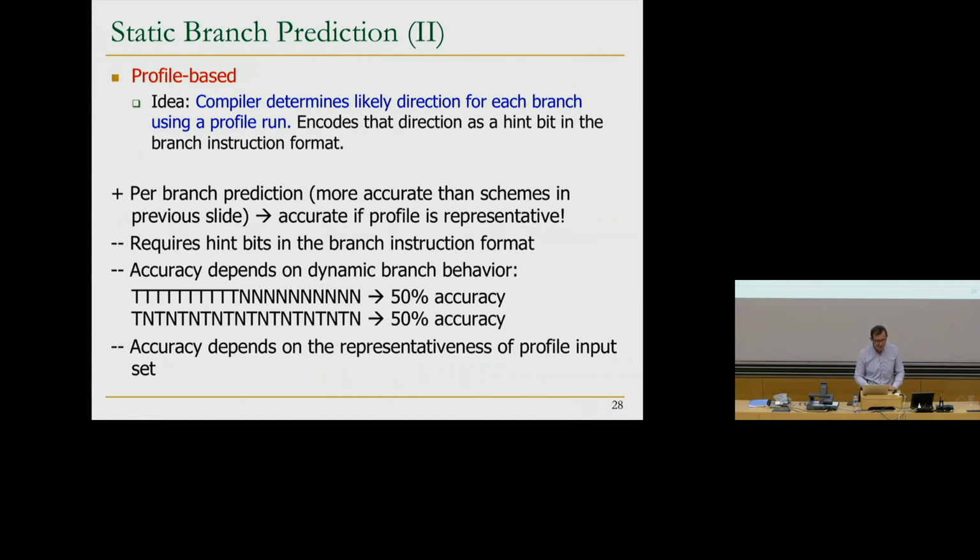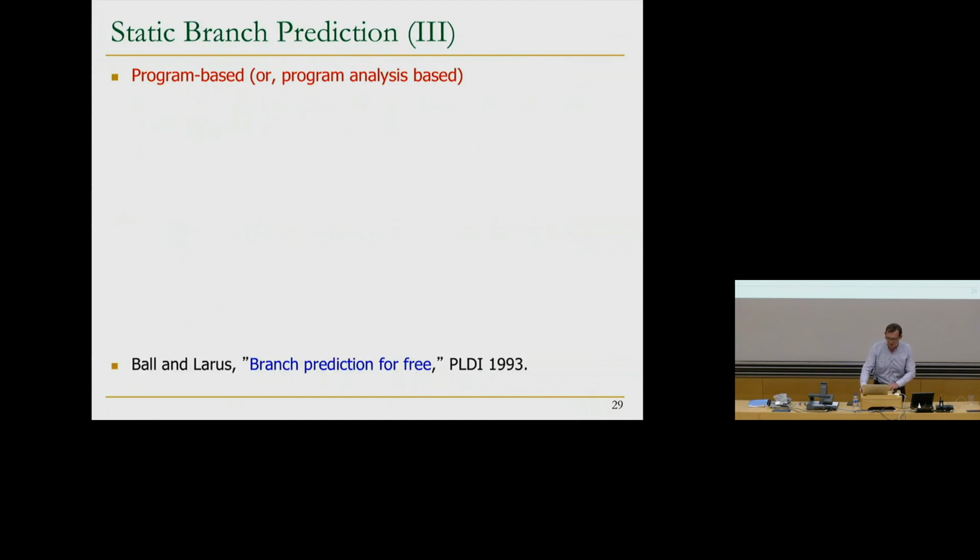So there are some cases where you cannot predict, but if you look at these patterns, they're very predictable, right? If the hardware sees this pattern, if you have pattern matching logic in the hardware, you can easily predict based on that pattern. In this case, you always say, I'm going to do exactly the opposite of what the previous outcome was. If it was taken, I'm going to predict not taken next time. If it was not taken, I'm going to predict taken next time I see the branch. Because you're executing the branch many times, you see this PC once, and the PC comes again at some point, and again at some point. So you always make a decision based on the previous time. Make sense? Okay, so keep that in mind.